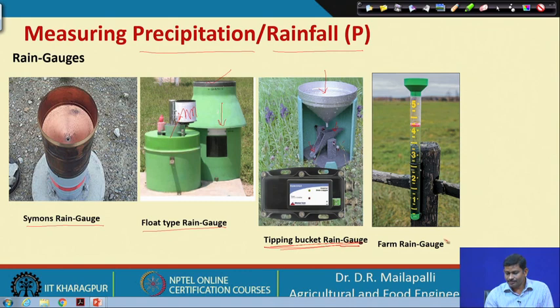And then there are simple rain gauges, the form rain gauges. It is a simple tube and a funnel, and this is pre-calibrated. It is marked 1 inch, 2 inch, 3 inch, 4 inch, 5 inch, and there is a red float. So, you can easily see the water surface here at 5 inch. This is very simple, so a farmer can maintain it within the field. The depth of water is converted into the rainfall depth, since this is pre-calibrated.